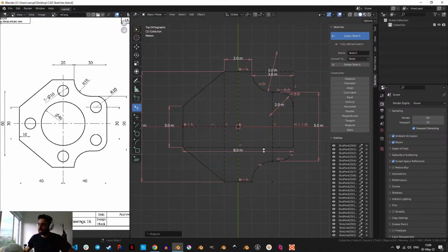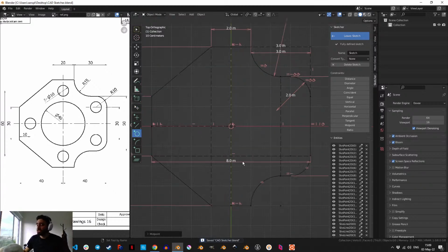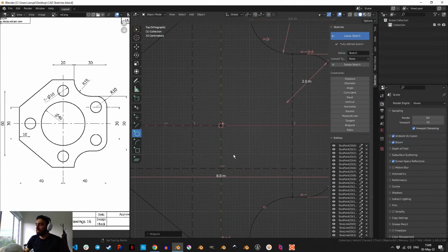Yeah, this is beautiful. Let's just save and draw these circles. The first one should be constrained right in the middle. And to do that, and this is something I had trouble with before, but now I know how to do it. When you draw an arc or a circle, the first thing you do is select the center of this primitive.